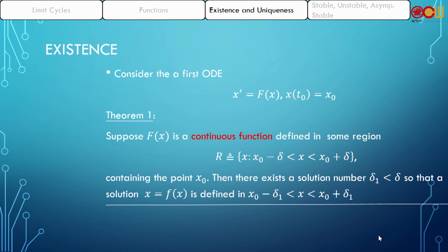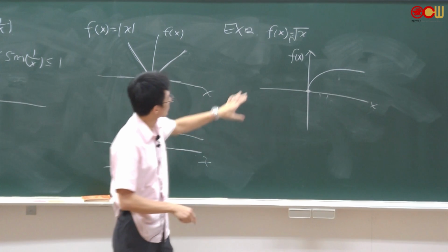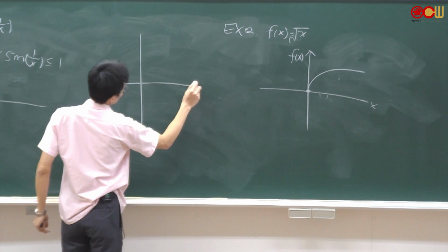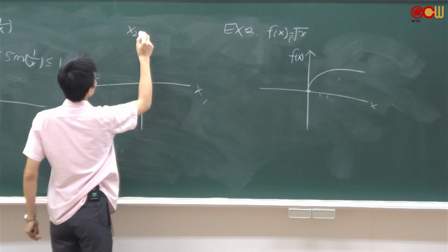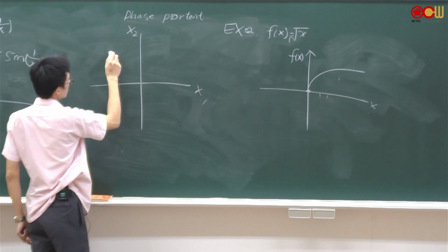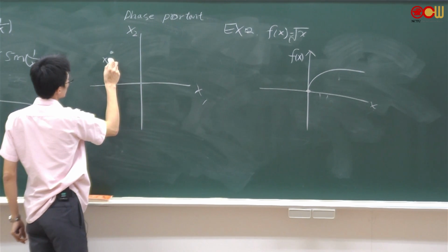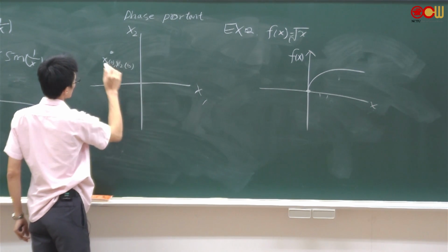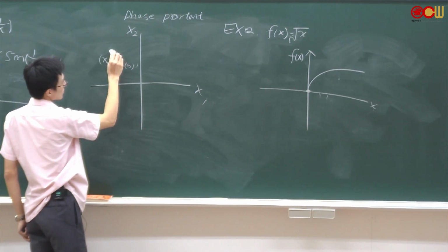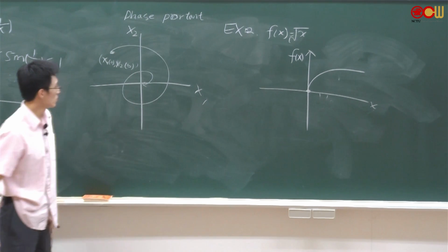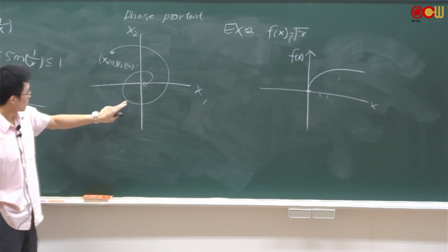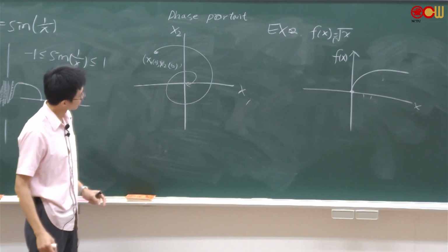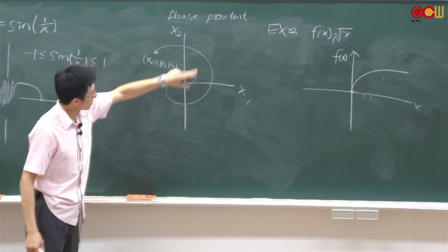In other words, given any initial conditions, no matter where in the phase portrait, x1, x2, we want to see if you can go to the equilibrium point and conclude that it's asymptotically stable or stable. So we want to evaluate given any initial conditions.